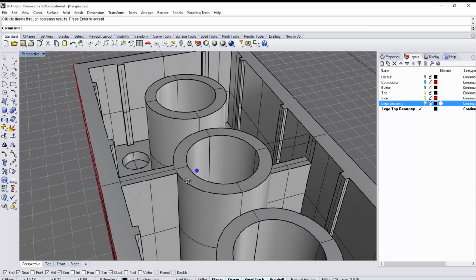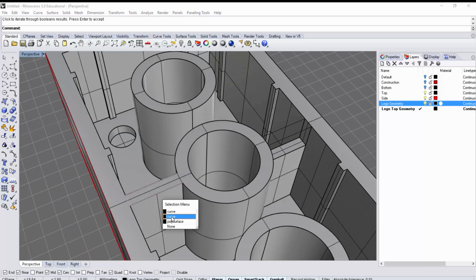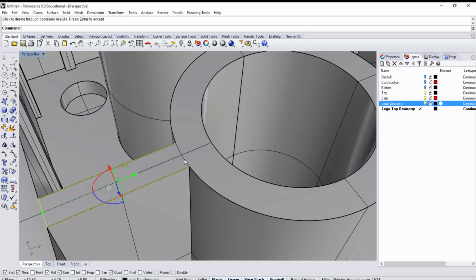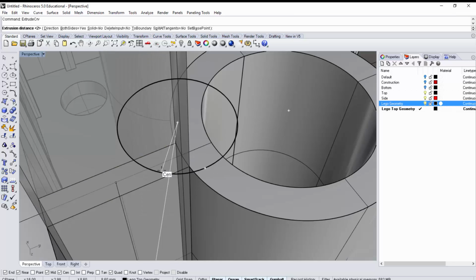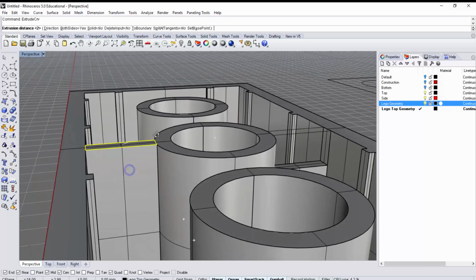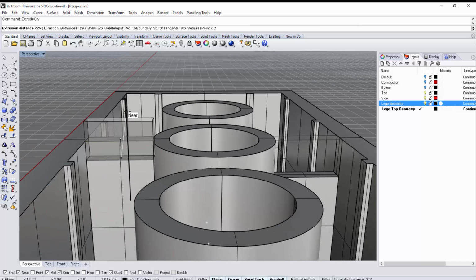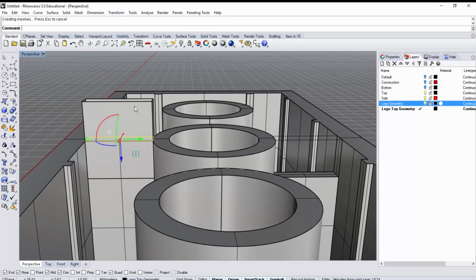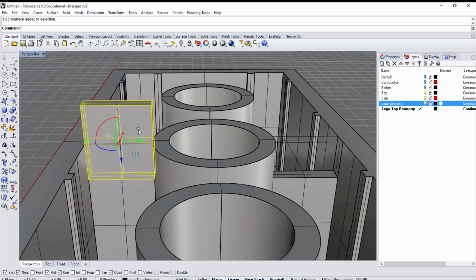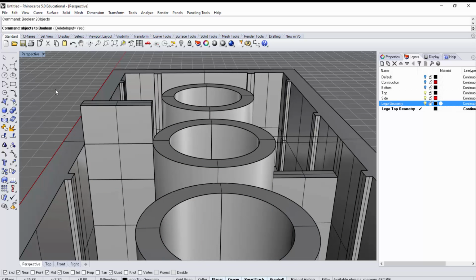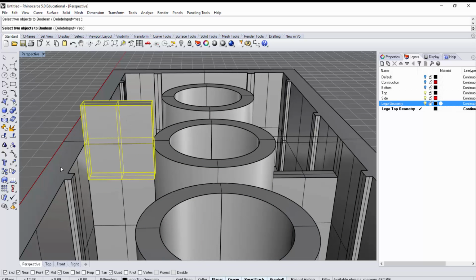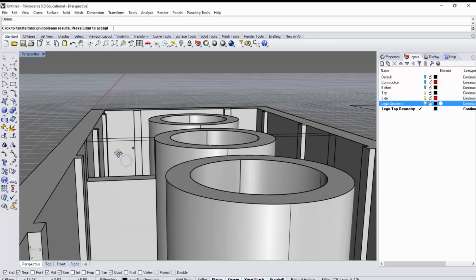Enter, and now I'm going to do the same thing over here. So first, grab your curve, grab your other curve, join them up, extrude curve both sides, by, what was it, 2? Say 2. Cap this off. It's nice and solid. And now we're going to Boolean two objects. So grab your cutting tool, then your object. Made a nice cut.